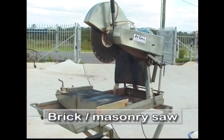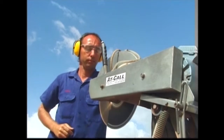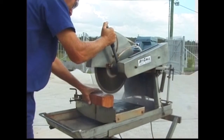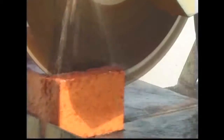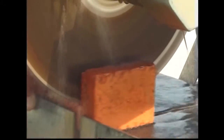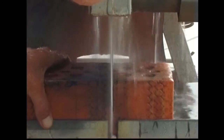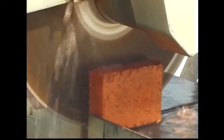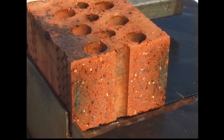A bench-mounted masonry saw also uses a water-cooled blade. The diamond dust bonded to the cutting edge of the blade makes light work of cutting brick and other masonry. Several light passes, each of about 5 millimeters in depth, is the best method of cutting. The diamond blade produces a neat and accurate cut.